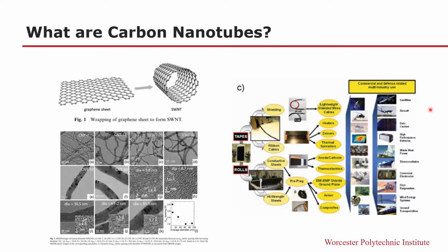This unique nanomaterial is most often noted for its incredibly high strength-to-weight ratio, about 100 times that of steel. It also exhibits very high stiffness at 1.2 terapascals and great fatigue strength, which is with high tolerance to large strains. They can survive temperatures up to 3,000 degrees Celsius and can transport a great deal of heat and electric current. Their electrical properties can vary from highly conductive, even superconductive, to semiconductive. The range of properties for carbon nanotubes are all highly dependent on their structure, and carbon nanotubes do not have a single structural format.